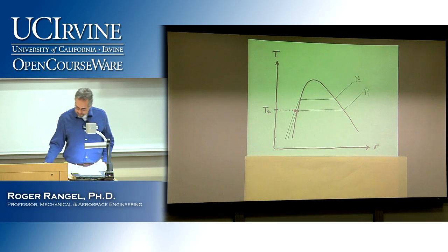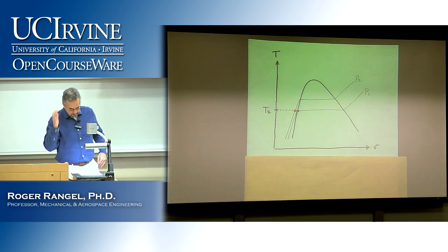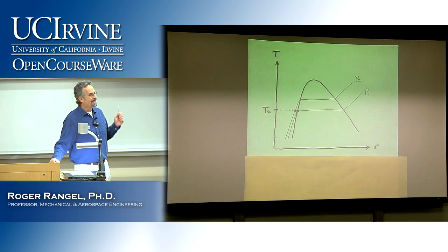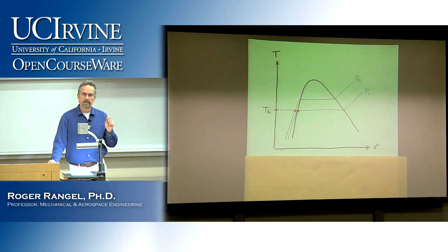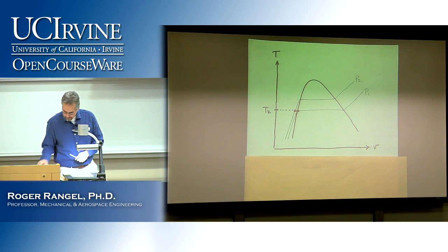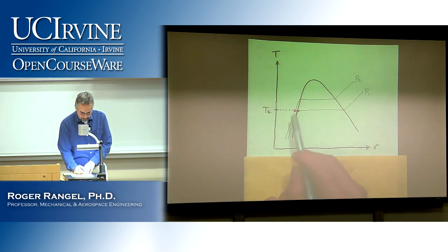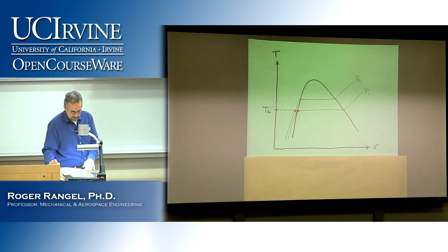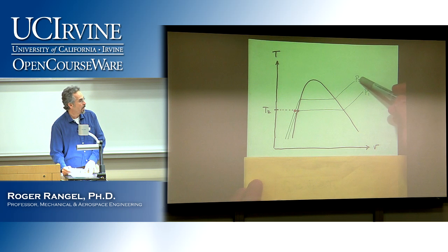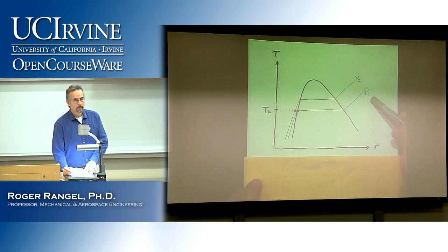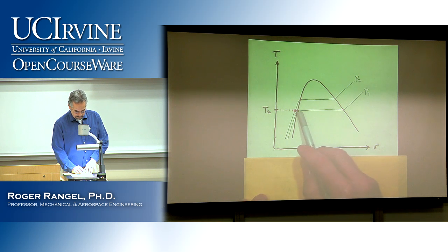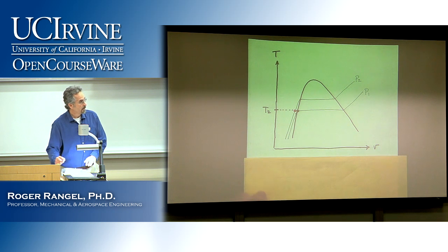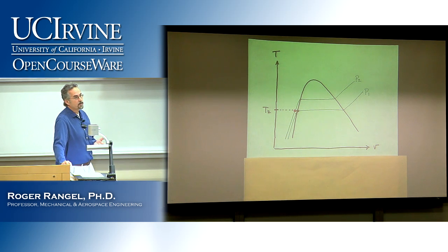So the two choices then, which are A and B. A would be at the given temperature. So disregard the pressure, use the temperature. That would take you from the red dot to the black dot because I'm reading it at the same temperature. I am disregarding the pressure, which was P2. Now I'm reading some value at P1, which is not my pressure, but I'm ignoring that value. I'm just taking the T2, and I'm reading VF right on the saturation line. You can see those are very close.